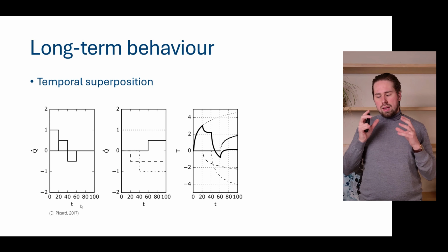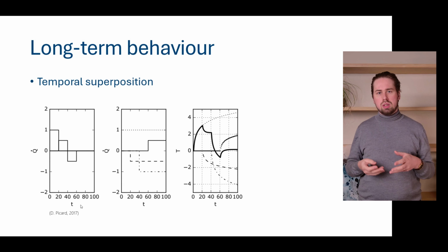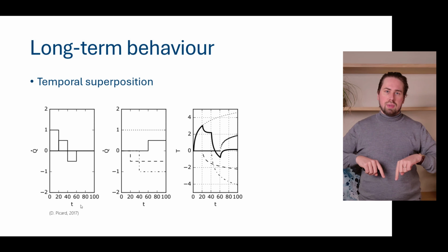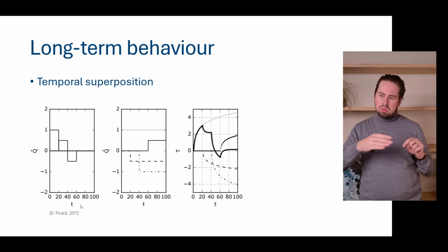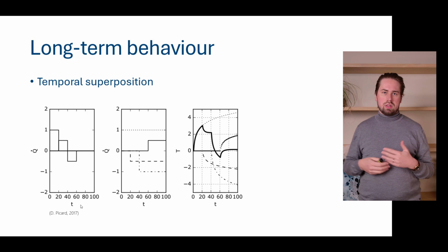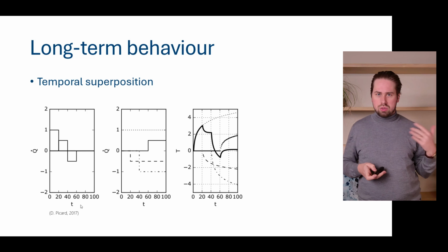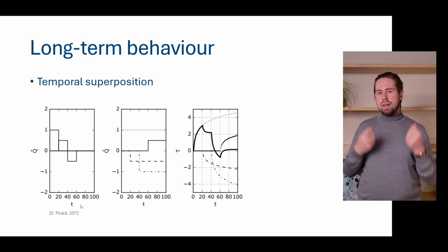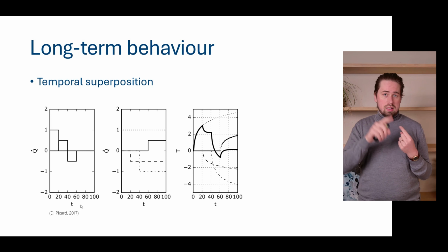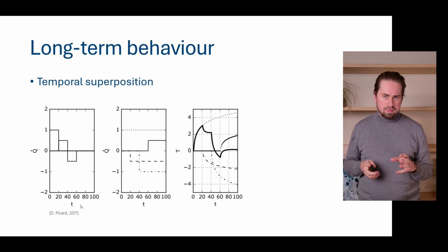Now, we talked about these G functions as well. They are all for constant power injection. And of course, if we extract power, the figure is the same, but it's just flipped, and the ground cools down year after year, but always less. But our load, in reality, is not constant. It varies from month to month, but in reality also from hour to hour. So how can we go from this constant behavior towards a seasonal and a yearly behavior? And that's what's called temporal superposition.